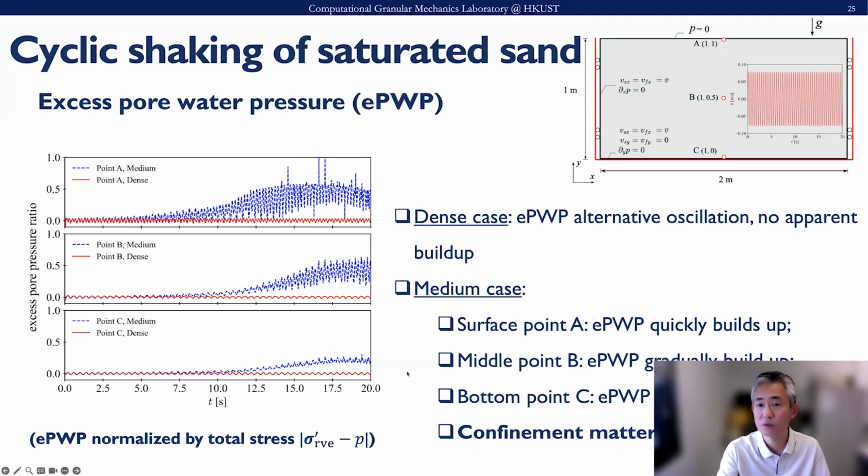So what we observe from the simulation is that the confinement matters, and also the density matters. Density and confinement, the two combined together, give us a unique indication of this state. So indeed, for saturated sand there is quite an apparent state dependency, with apparent features that affect the mechanical response, like liquefaction.